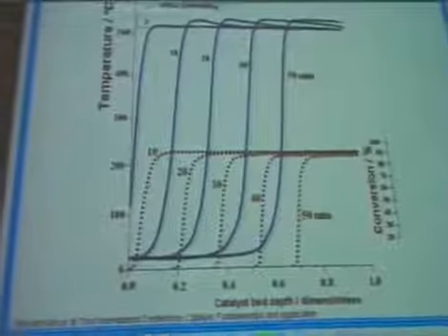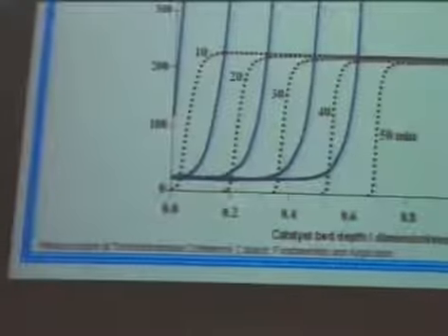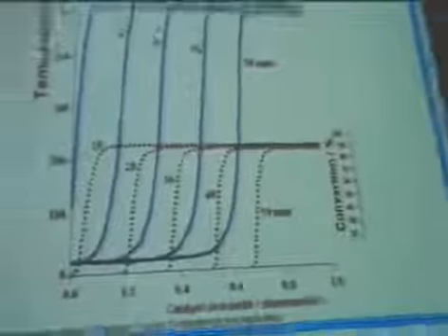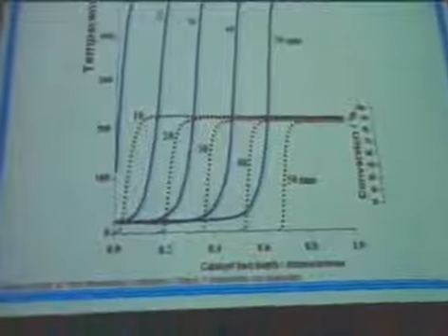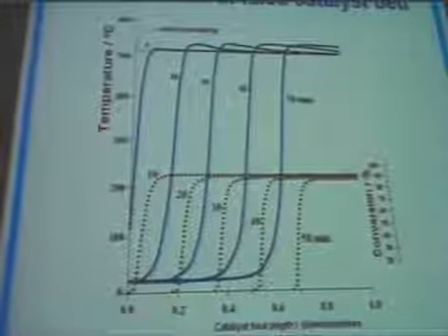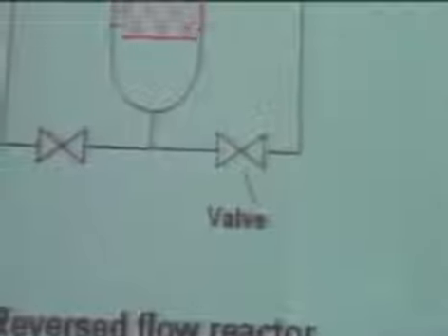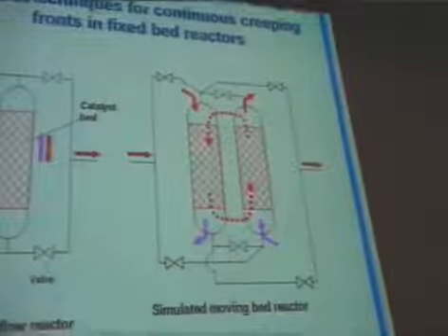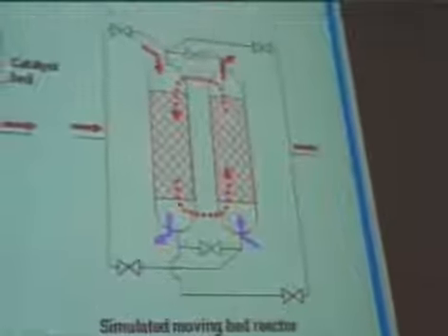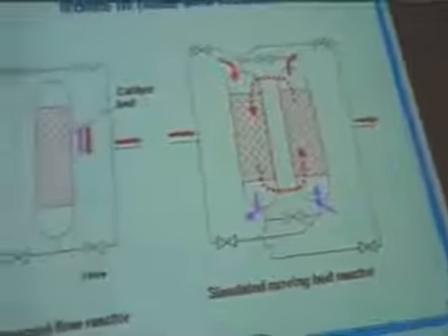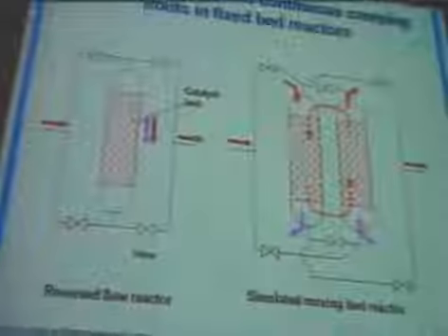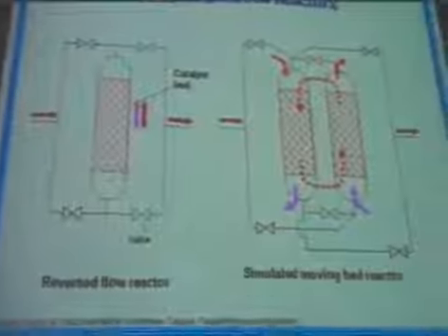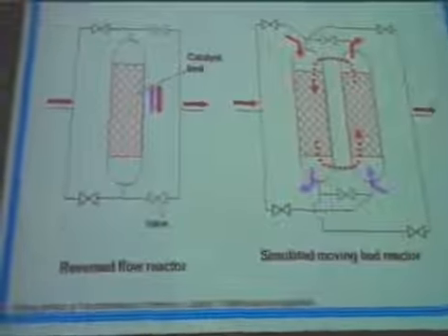And there are a few methods to hold this heat wave inside the packed bed of the catalyst. We will return to this idea when I discuss the real application. These are a few methods of having the hot place inside the packed bed. It's the well-known reverse-flow process, periodically changing the direction of the flow inside the packed bed of the catalyst. And this is the reason why, at cold inlet and cold outlet temperature, I have high temperature inside the packed bed of the catalyst.